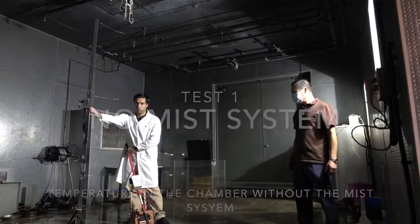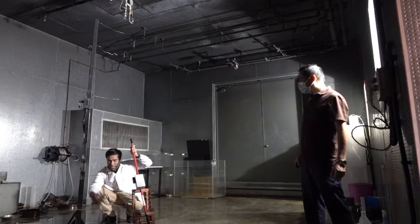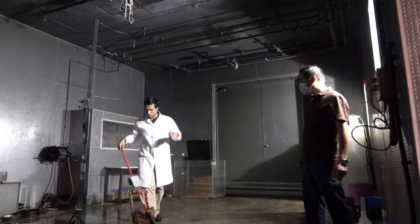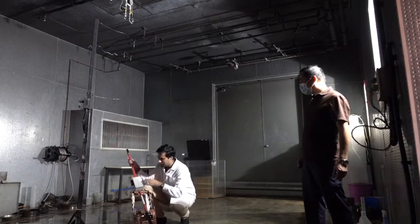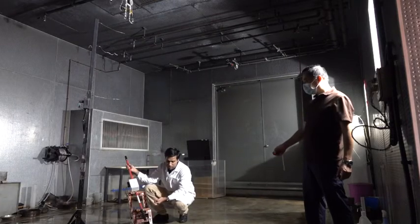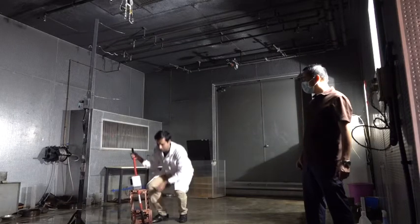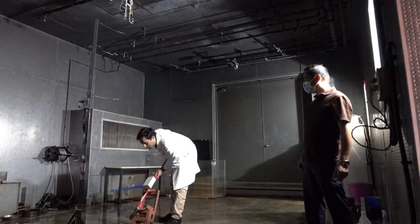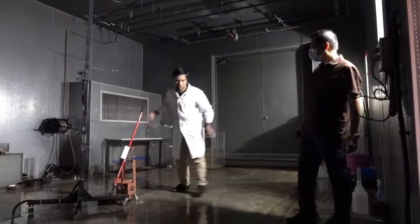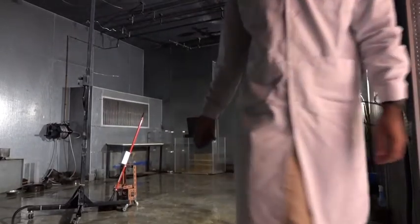Here this is a thermocouple, as I told you earlier, where we measure the temperature, and here we are taking 200 ml of propanol, which we will burn, and then take the temperature from the thermocouples to see how the temperature rises. We will initiate the fire with this electric igniter. You can see how it will ignite. This electric igniter will be used with the propanol and the fire will start. So let's begin with experiment 1. During this time we will measure the temperatures from the data logger which I showed you earlier.